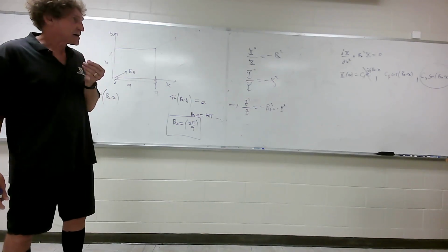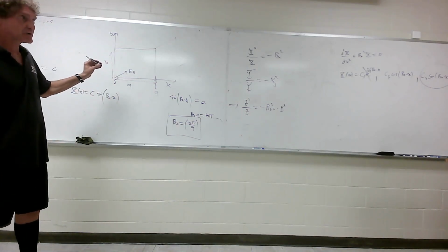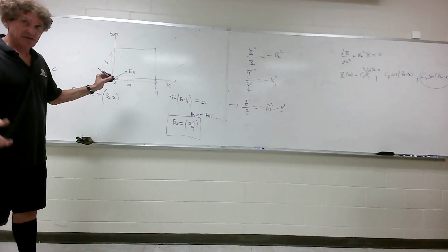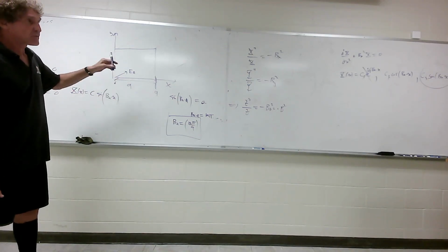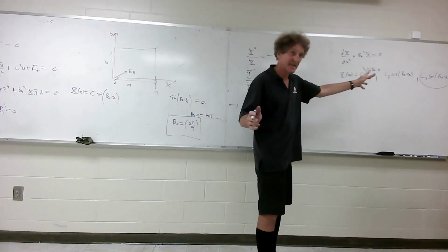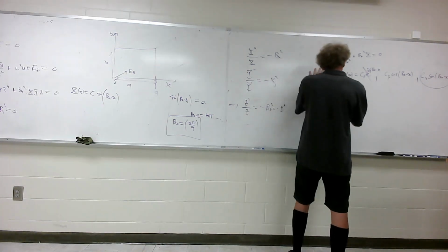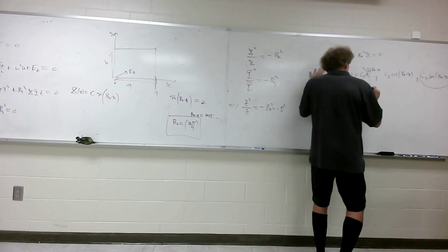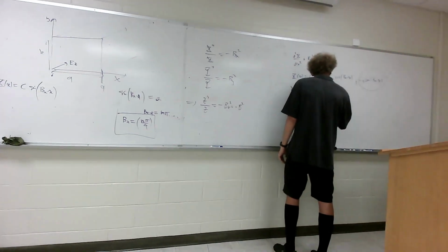That's beta x. Now, think about the y. Remember, we're talking about a separation of variables to get Ez, right? Well, the y component, the functional form of y, will also have these possible solutions, but only the sine can be possible for a TM wave. So then we can say Y of y will have some constant, call it C4, it doesn't matter, they're just arbitrary constants, times sine of beta.